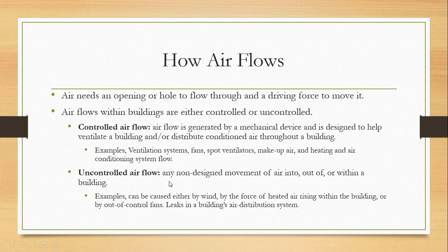All right, for example, it can be caused by wind or by the force of heated air rising within the building, or if you have malfunctioning equipment. So it's uncontrolled. Also, it can be uncontrolled if you have leaks in the air conditioning system, the air distribution system. All right, so it's uncontrolled if it's really by natural forces, or if you have malfunctioning in your HVAC system.